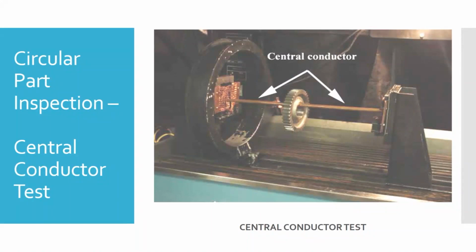If you run a fair amount of current through this, what's going to happen? It could, before it melts, what'll happen? Okay, and when a metal gets hot, particularly a brass or a bronze, it can get soft and it can start to sag. So you need to run the current, but you've got to be careful not to overdo it. And the skinnier the rod, the more likely it is that you'll overheat it.